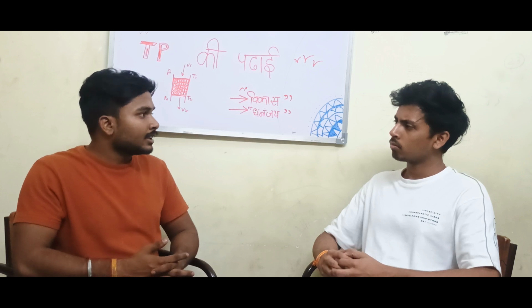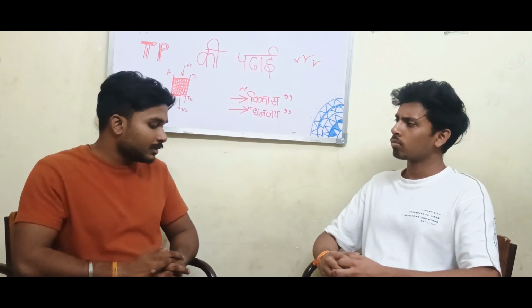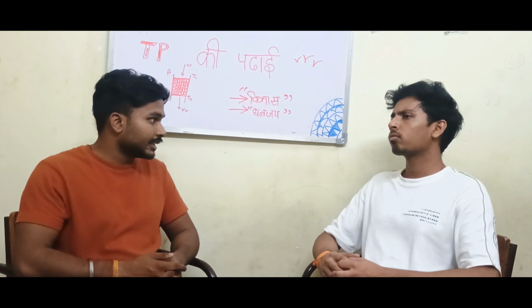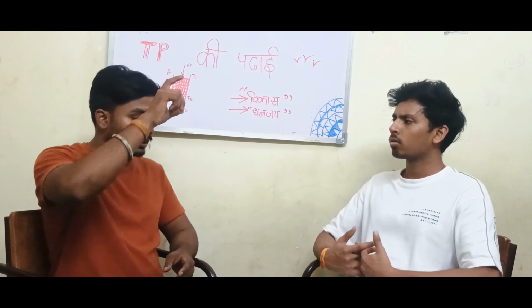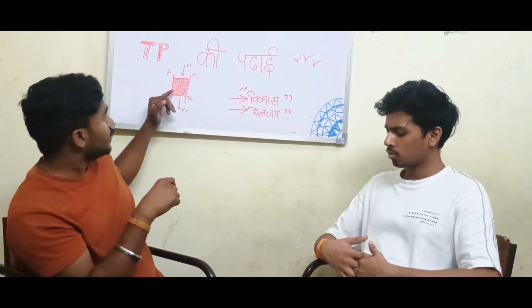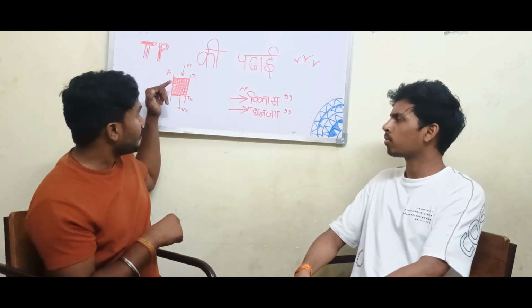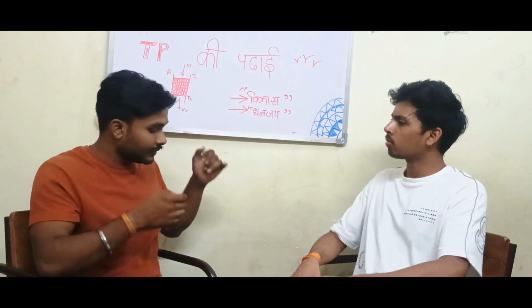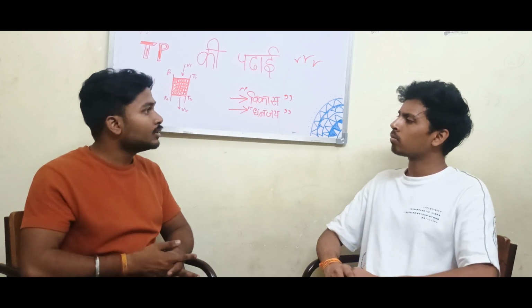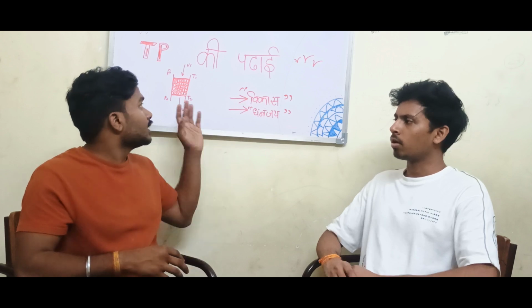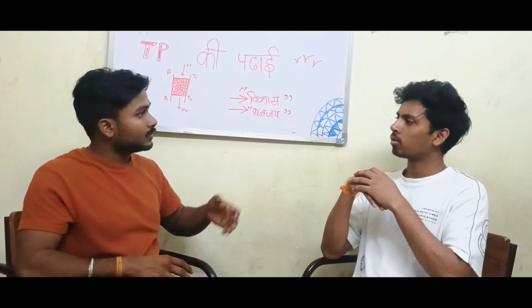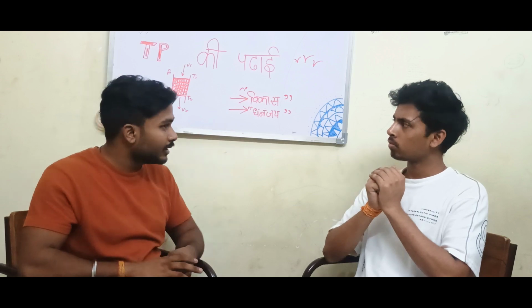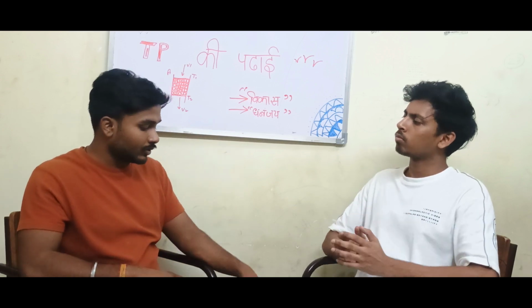For experimentally determining the mass transfer coefficient, there are some techniques such as tracer techniques. You can measure the concentration profile along the column, and you can use a step or pulse input method, giving a step response, to get the experimental result for the mass transfer coefficient.